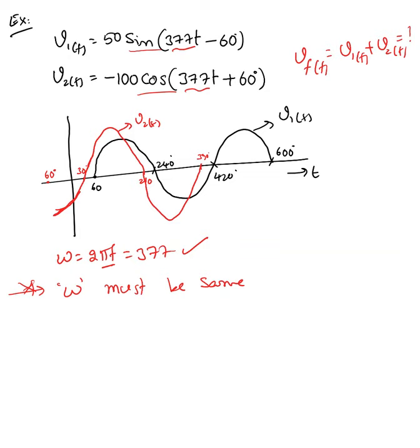So when you bring a new generator online, that means connecting it to the grid, and our frequency here in the United States is 60 hertz. The incoming generator frequency must be 60 hertz, or I think they might accept around 59.99 to 60.01.